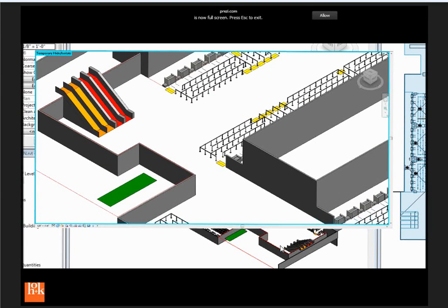We have to let people know how they're going to get into this thing. So there's certain parts that we have to put in. These little families here we developed kind of custom, but they're just generic components right now. Generic model adaptive components. It's the only way to really get a plane in Revit. If you ever wanted to get a single surface in Revit, the simulation engine we're using needs that. So that's actually quite difficult to do. So you finally kind of hack it together. But when you're doing a simulation, you've got to give them a portal. So that's a way in or a way out. It's where people kind of are born or die.